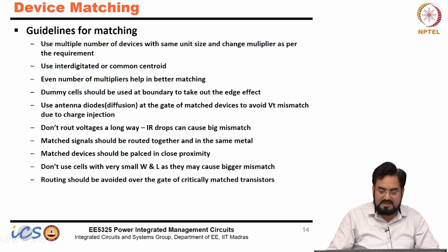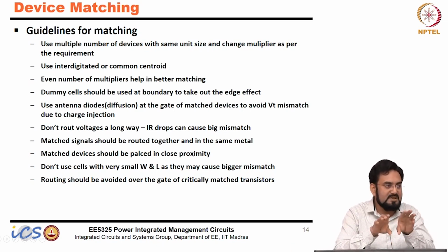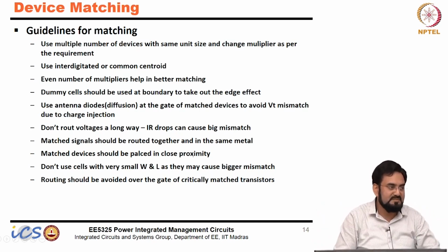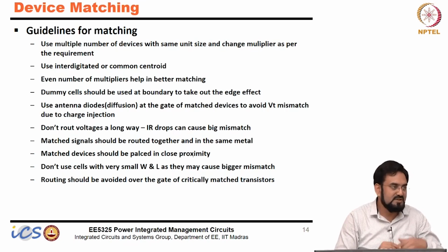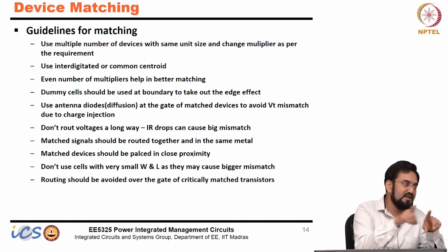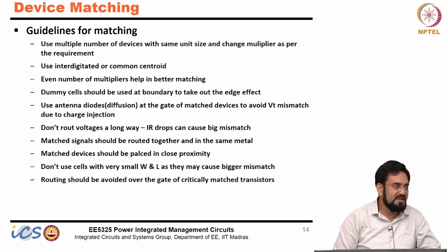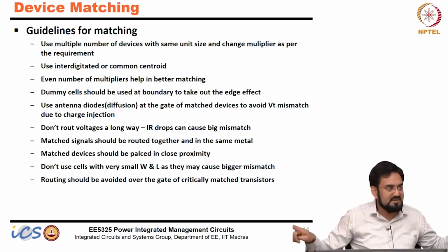Matched devices should be placed in close proximity. Okay, so don't try to create too much space between the two matched devices. Make sure they are as close as possible. There are some rules, like what should be the spacing between one layer and another layer. So follow the minimum rule, don't just keep them away.